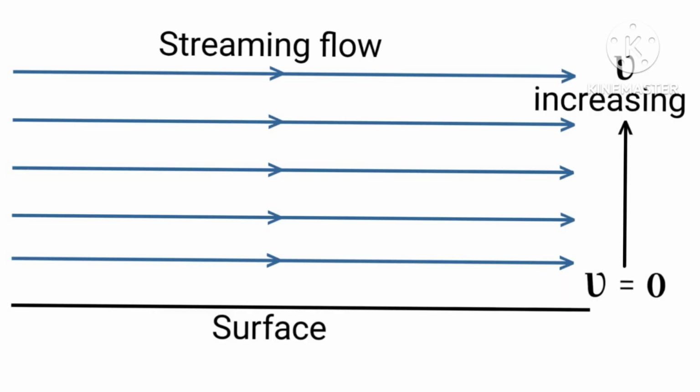When a liquid flows in a streamlined manner over a fixed plane surface, it is seen that the layer of the liquid in contact with the surface has no motion due to the force of adhesion. The layer remains at rest. However, the velocities of other layers are proportional to their distances from the plane surface. As the distance increases, the velocity of different layers also increases.